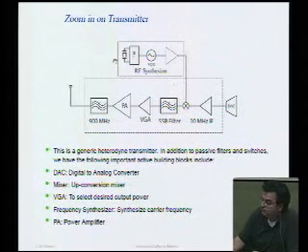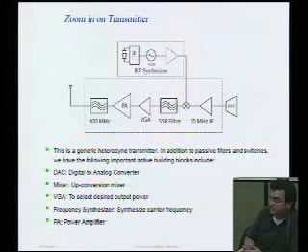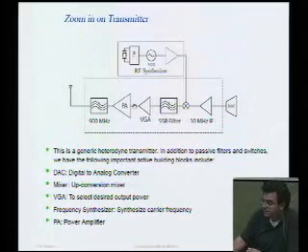There's that little crystal symbol that somebody brought up. This is our precise reference frequency. So now we've translated our, let's say, baseband signal, the bits, into a precise RF signal, very precise frequency. And we can also set the amplitude very precisely with, let's say, a VGA, a variable gain amplifier.